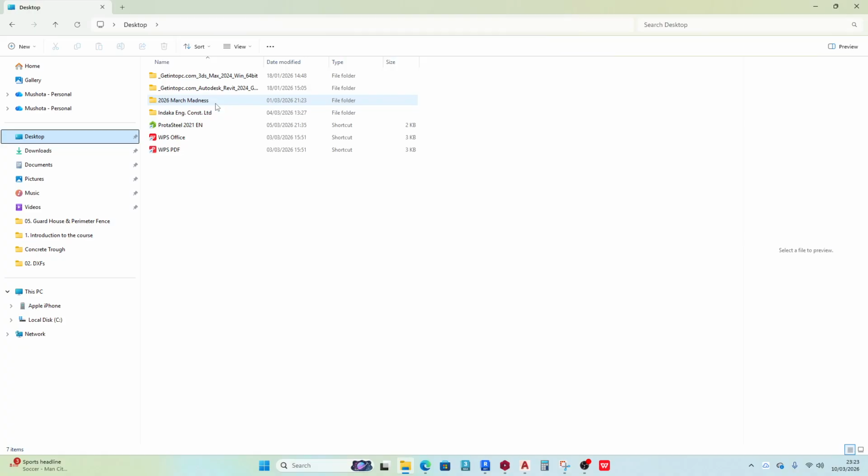When you import a DXF file into Proto, as long as you're on different layers, you can load in grid lines, grid IDs, and structural columns, and if you incorporate some beams, structural beams also. In that video, we ended by saying we would be adding levels